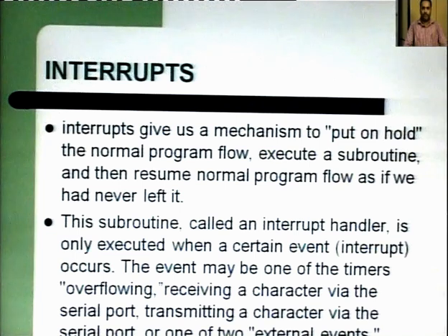The subroutine in this case is called an interrupt handler. It is only executed when a certain event called an interrupt occurs. What are these events? They may be the overflow of timers, which are internal interrupts, or receiving a character by the serial port, the serial port reception RxD pin, then transmitting through the serial port, then two external events, meaning two external interrupts, and